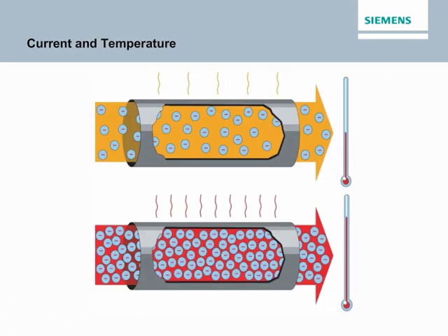Some of the control components covered in this course are designed to protect motors or other equipment. In order to understand these control components, you must have an understanding of some common circuit faults. To begin with, current flow always generates heat. The amount of heat generated is proportional to both the amount of current flow and the resistance of the conductive path. Because conductors can be damaged by excess heat, each conductor has a continuous current rating, also called its ampacity. Excessive current is referred to as overcurrent. An overcurrent may result from a short circuit, overload, or ground fault.